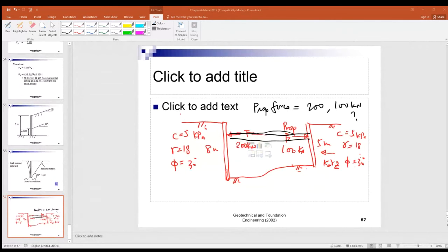And also any slope surface properly maintained should be safer than those slopes without regular maintenance. Particularly any blockage in the surface channel, where the rainwater could be blocked off, right, and cannot discharge downwards. So there will be large amounts of rainwater seeping into the soil, and that will give rise to the groundwater table. Now that will trigger off the soil slope instability.